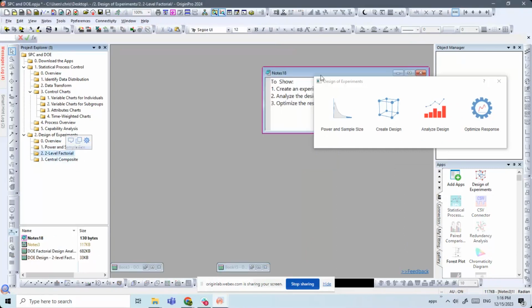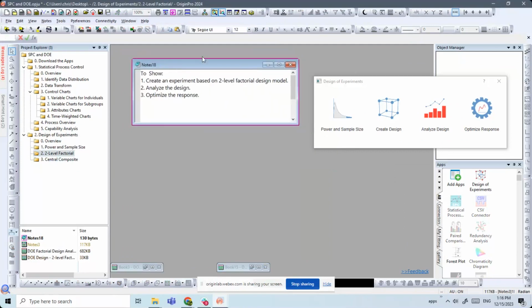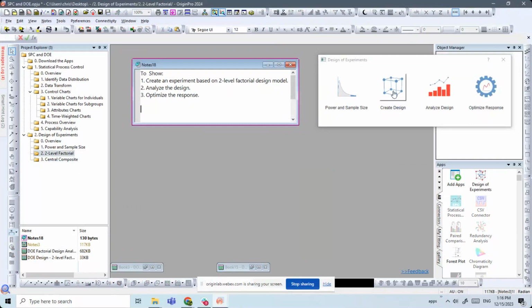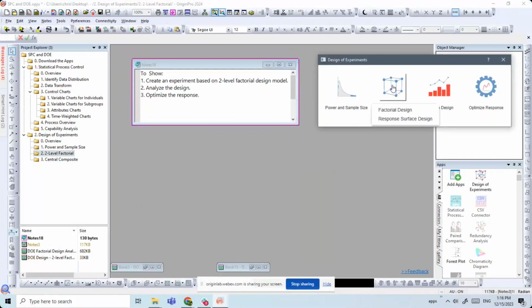Yeah, let's quickly go through one example of the experiment design. Okay, let's choose a signal tool here. There are 2 designs that you can choose from. So the factorial design is more simple. Once you are able to select the important factors of the design, then you can go to a more advanced design, where the second order of each factor will be included, then you can use the response surface design. So start with the factorial design.